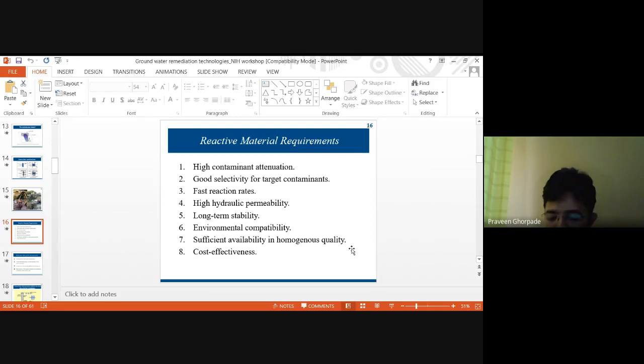And if it does not, then you can engineer that particular system by introducing some materials which are capable of treating it. For example, if you look into seawater intrusion problems in the coastal region, in Karnataka, our own state, we have some problems in Karwar, these districts where coastal zones are there. The seawater gets mixed with the fresh water, and especially in this belt of Karwar and Goa, you have lateritic zones, and then we need to understand the soil chemistry, exactly how laterite works. This is a very interesting study in terms of materials. Now, if you understand the reactivity of these materials for different pollutant systems, the same materials can be used in PRBs, permeable reactive barriers, also. So this is how exactly it goes.